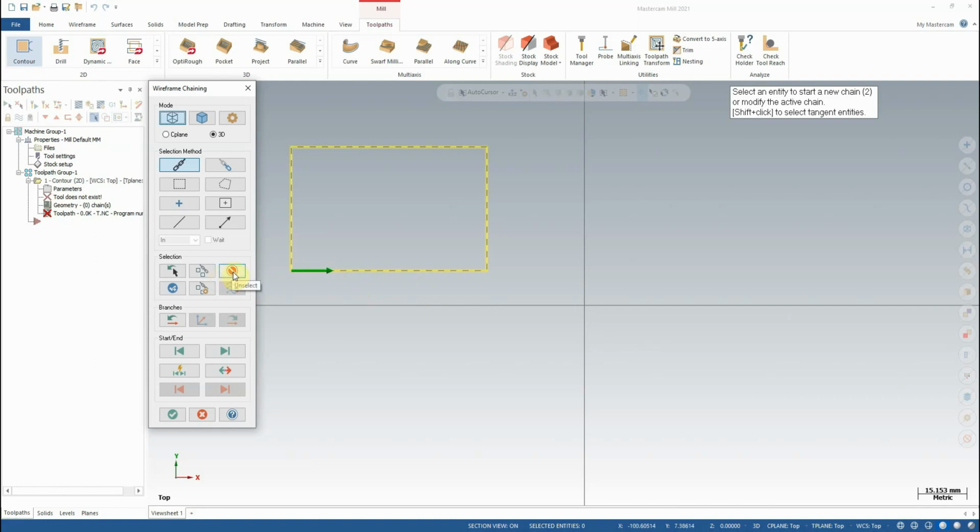So just as a quick reminder, if we imagine the tool turning, remember that our tools are going to turn in a clockwise direction, so we can move our mouse in a clockwise direction, and our goal is to have the tool always climb milling around a feature. So when we're cutting the outside of a part, that would mean we want to travel around the part clockwise, because the cutter, as it comes around, it's grabbing into the material on the leading edge like this. If you picture that, the reason why it's called climb milling is it's climbing up the material as it rotates into it.